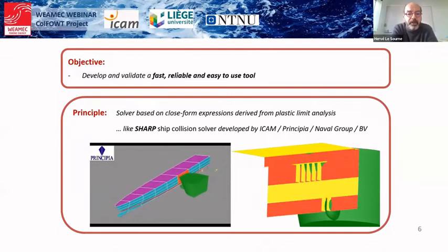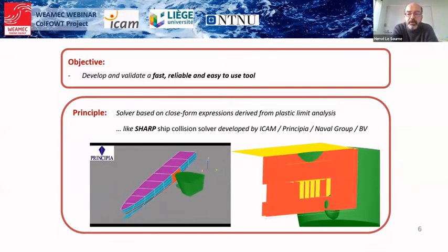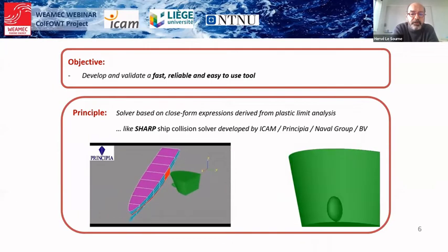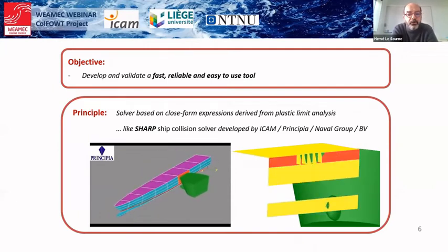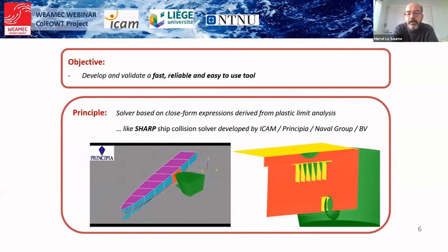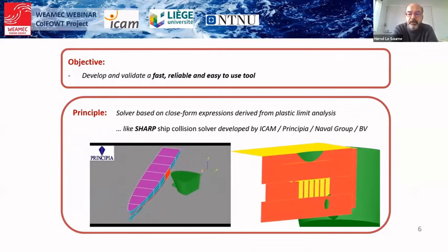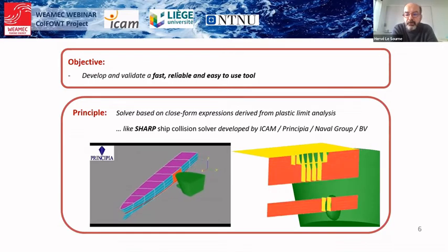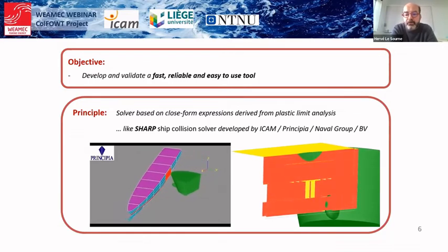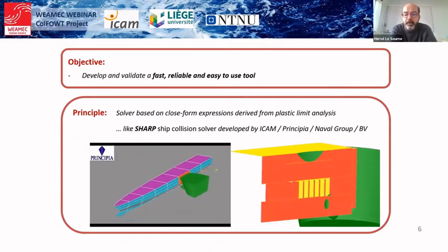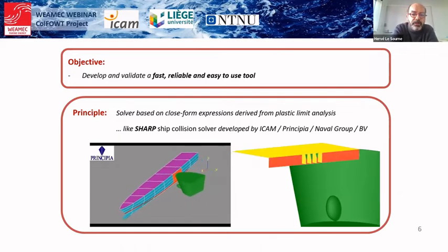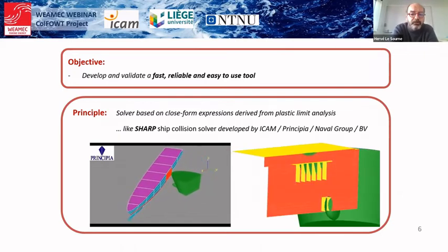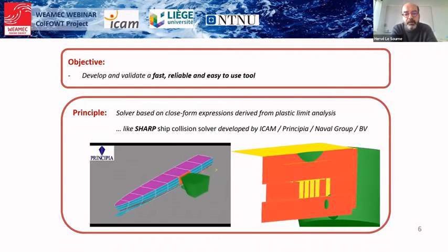So the idea is just to develop a semi-analytical solver, which is based on closed form expressions derived from plastic limit analysis. And these analytical expressions will give the resistant force of macro elements as well as dissipated energy as a function of the penetration of the ship into the structure.